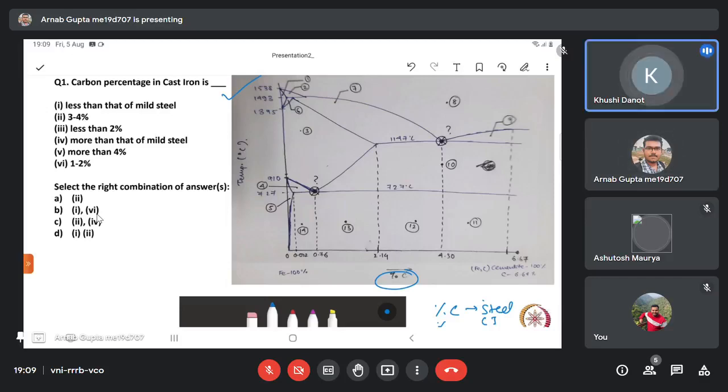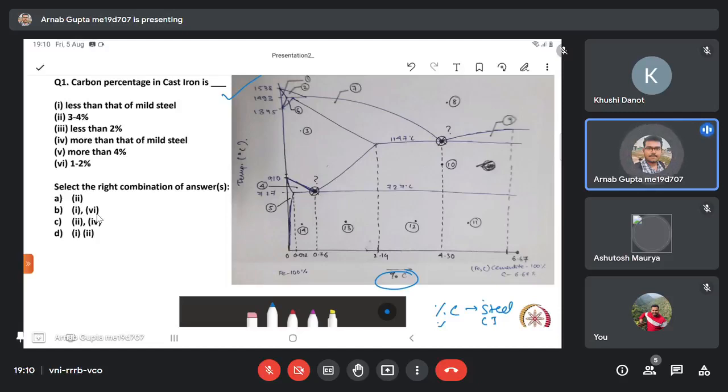Sir, cast iron contains 2% of carbon. No, it's not correct. It's more than 2%, right? Still it's incomplete, till 6.67%, because if we go beyond that the material will become brittle and not applicable for common engineering applications. Although its strength will increase, it will become too brittle to be used in day-to-day engineering applications.